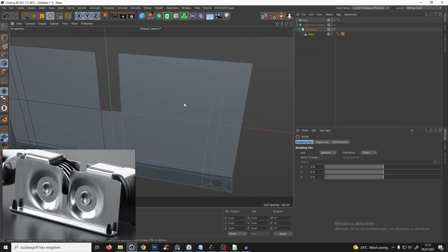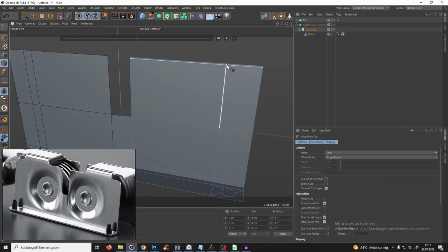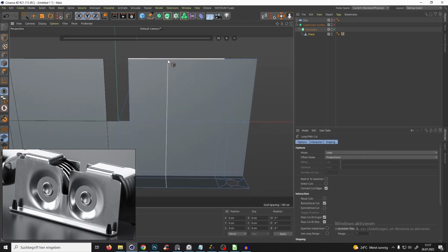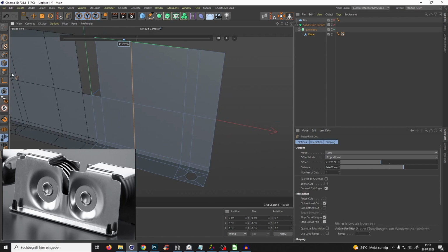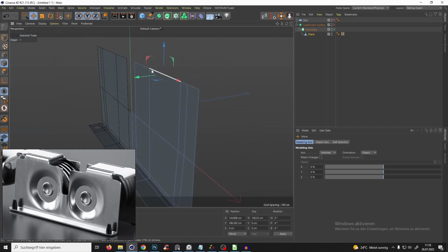That's what we need. Now we can create a new cut again with the loop cut, because you see we have here already the point which we need for this thing to come out, and now we need like one loop cut more which goes here, and also we can add the disk then later. So yeah, maybe something like here, but I also want to have those edges because this distance is a little bit too long, just a little bit more to the outside. So yeah, we can take now